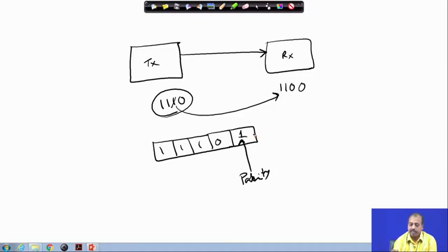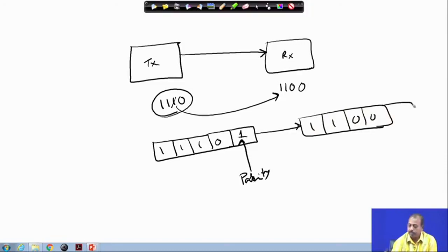So, that at the receiving end, assuming that this parity bit has been transmitted properly, the received bit pattern is something like this. So, you have got 1100 and then parity bit is 1. But from this, if we calculate the parity bit, since we have taken the protocol that we will always be transmitting an even number of ones, based on the received bits, since these 2 bits are 1, this bit is expected to be 0, but the receiver finds that it has received the bit 1.